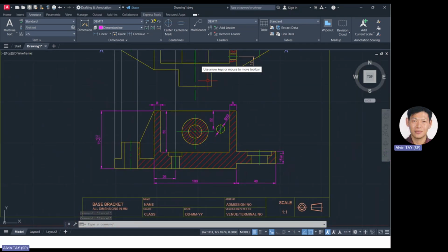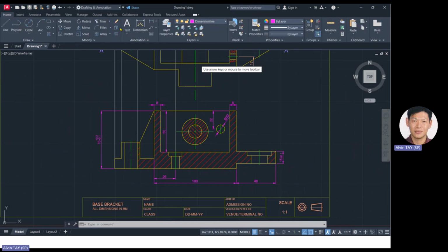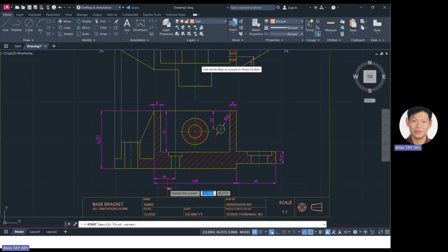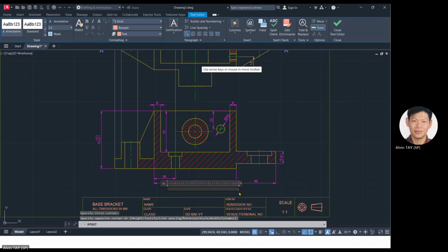Okay, then you label. Add text. So label this view as section view. If you want to type section view, if not, you just type view A, you can section view A-A. So this is going to be 5M. Underline. It does not matter whether you underline or not. For me, I prefer to underline.